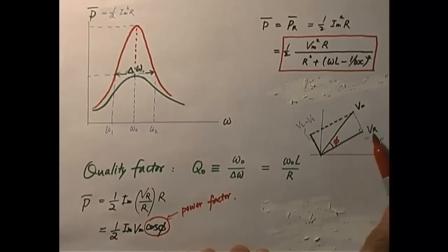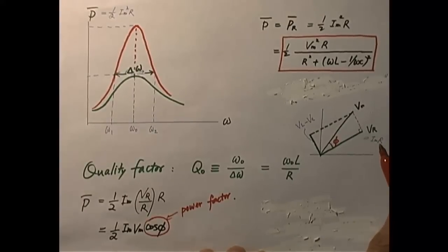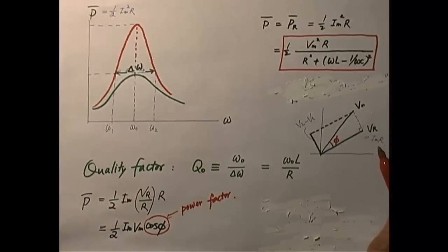And then when is VR equal to 0? That means there is no resistance. So you have a purely non-resistive circuit, and of course that circuit has no power consumption, because nothing is turned to heat, and therefore the average power consumption would be 0. So it makes sense in either special case. That is the idea of the so-called power factor.